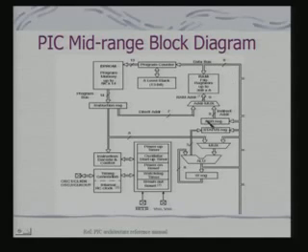We shall come to the exact mechanism used for indirect addressing when we discuss the instruction set of the processor. So at least from this architecture, what is straightforward is that I support immediate addressing, direct addressing and indirect addressing, and primarily my operations use this RAM, which is nothing but the same register bank of a RISC processor.